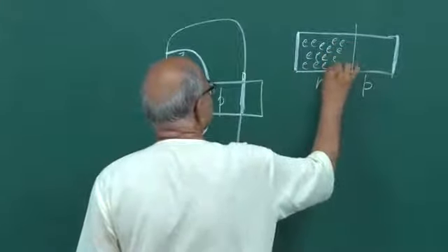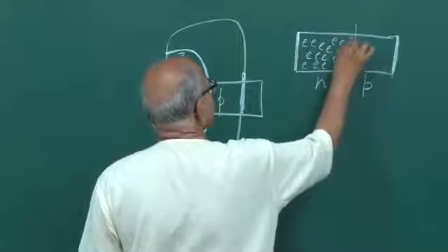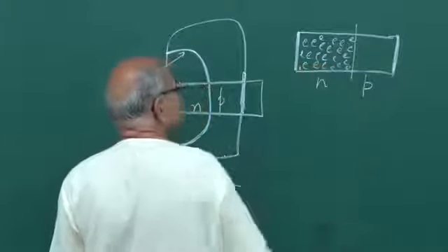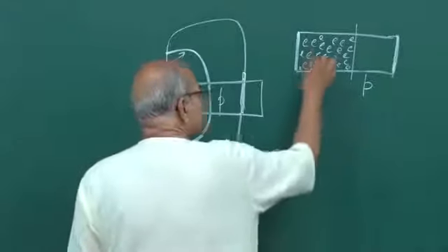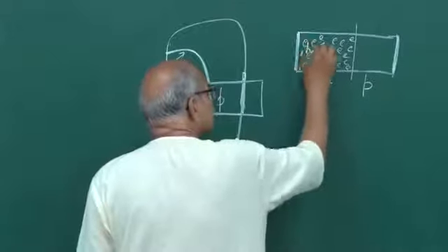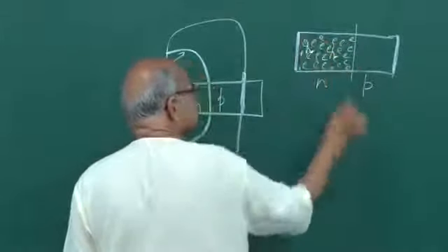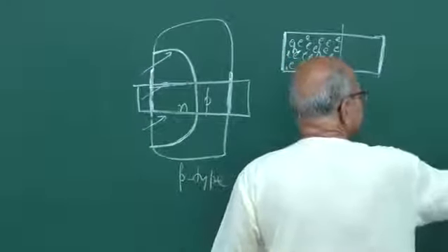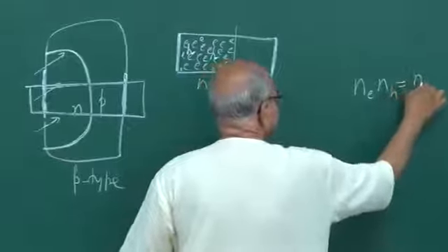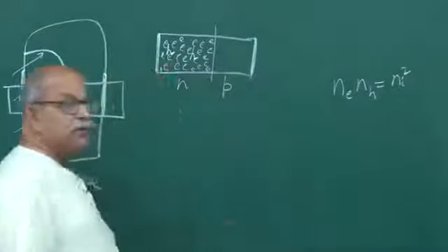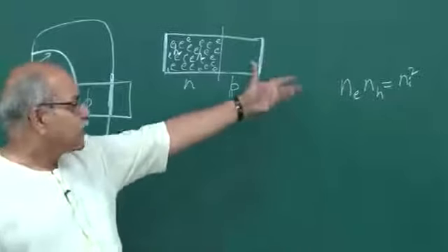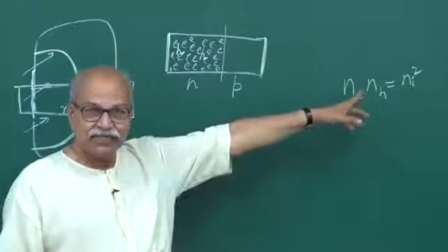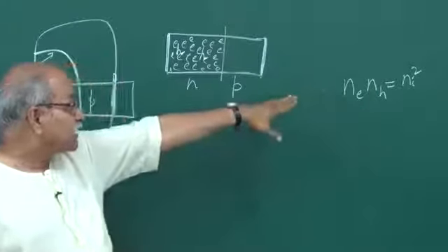Because of those pentavalent impurities, you have large number of free electrons here, and you have some holes here in between, small amount. Remember, n_e times n_h, that is fixed, n_i squared. And for a ppm type doping, we had calculated that the number of holes reduces to few thousands per centimeter cube, but they are still there.